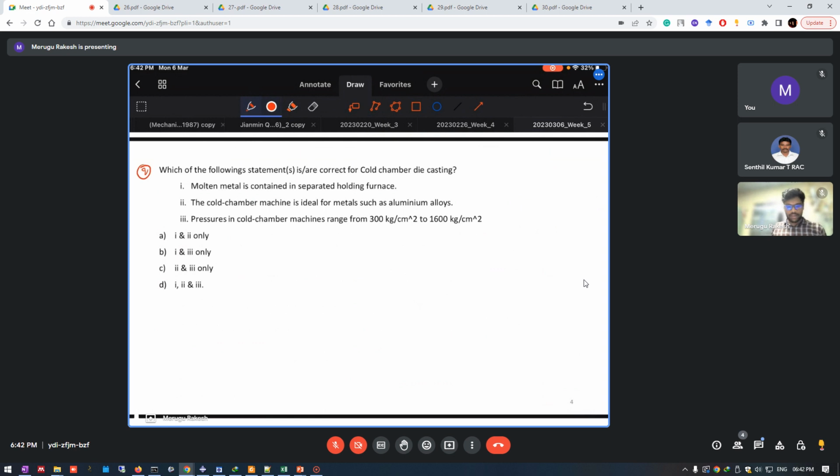So let me read. Which of the following statements are correct regarding cold chamber die casting? Molten metal is contained in a separate holding furnace. That is true. The cold chamber machine is ideal for metals such as aluminum alloys. Yeah, this is also true.